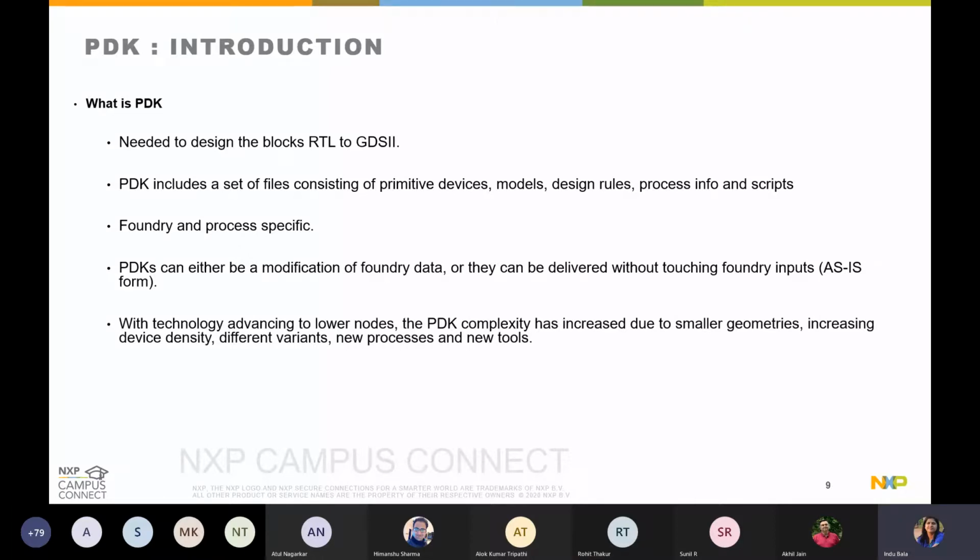As said, as the technology is advancing to lower nodes, the PDK complexity increases, because we are going to smaller geometry, and not just smaller geometry, but different patterning and everything. So PDK complexity increases especially in terms of how the device layouts are being created, how your design rules are defined, or how you do your LVS and other comparisons. With every time you go to a lower node, the PDK complexity does increase multifold.